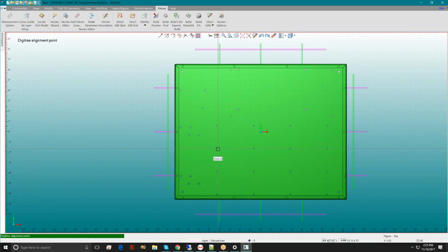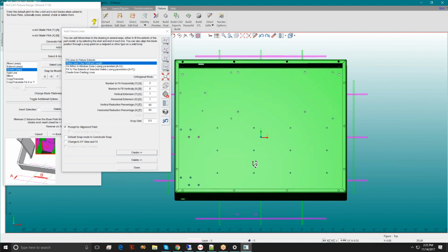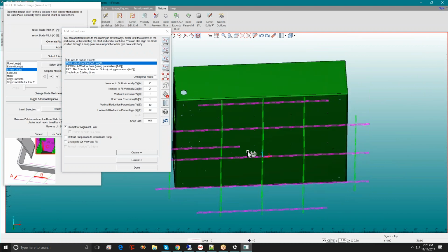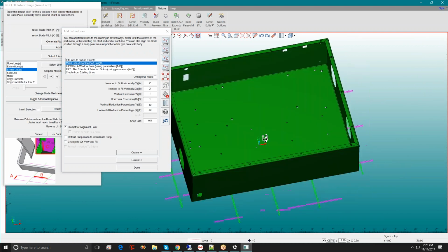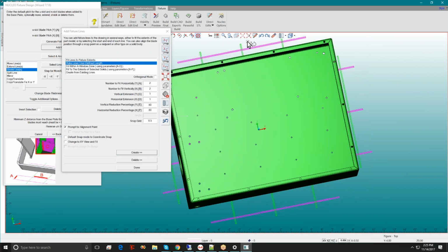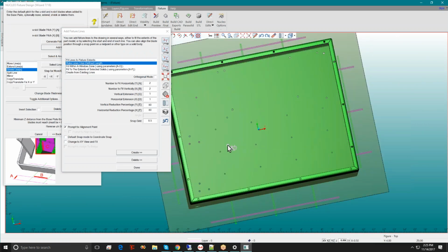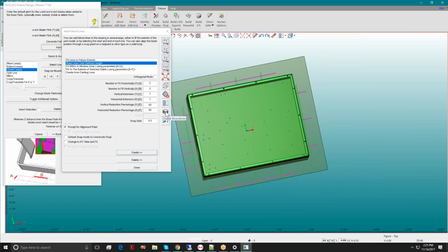So that's why you can do that. You could say then do from the end of there to my alignment point. I want to go, say, from the end of that to, I don't know, the midpoint of that. It's drawn a line that's gone from there to about here. You can't see it's underneath. So that's how you can do user defined lines at a given length. And then once you're finished, you could always right click in the background and say show all hidden bodies, and then the boundary's back. I just recommend, to be honest, just turning them off with the layer.